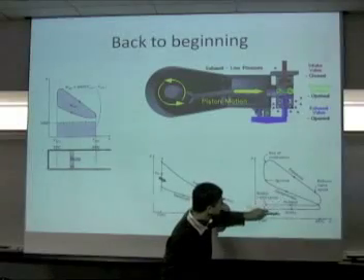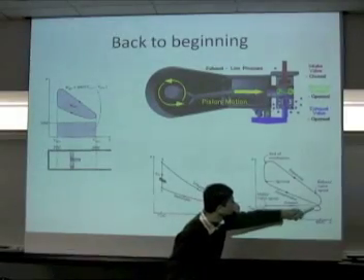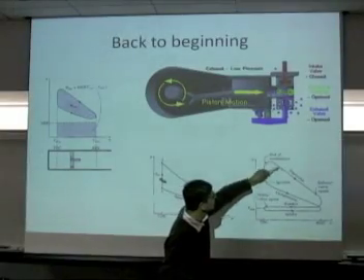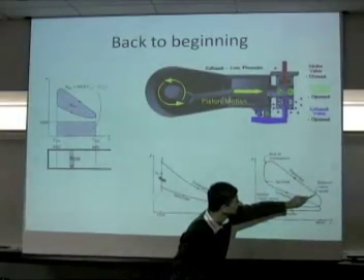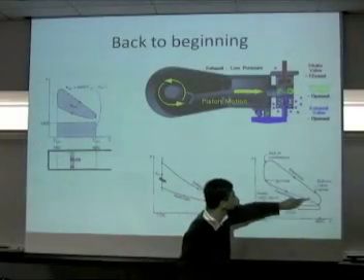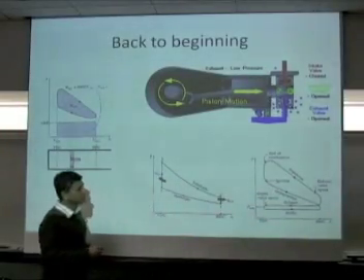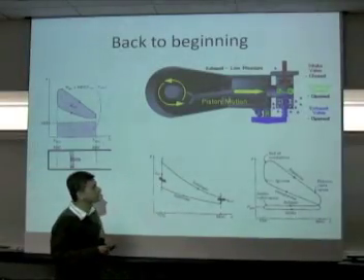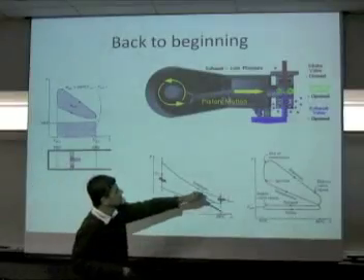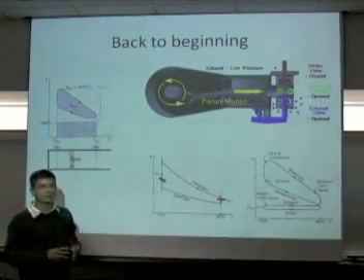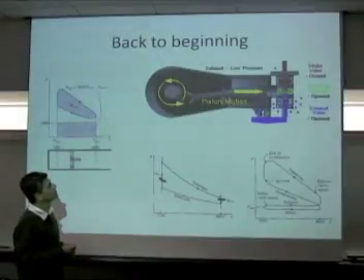So if you see the real cycle, you've got a little bit more complex things going on, where the ignition occurs here, the end of combustion occurs here, the expansion occurs here. This is where the exhaust valve opens and the intake valve opens, and then you get intake and compression. So it's a little bit more complicated than what happens in a simplistic thermodynamic cycle, but this cycle explains what we really saw in all aspects of the four strokes of the engine.